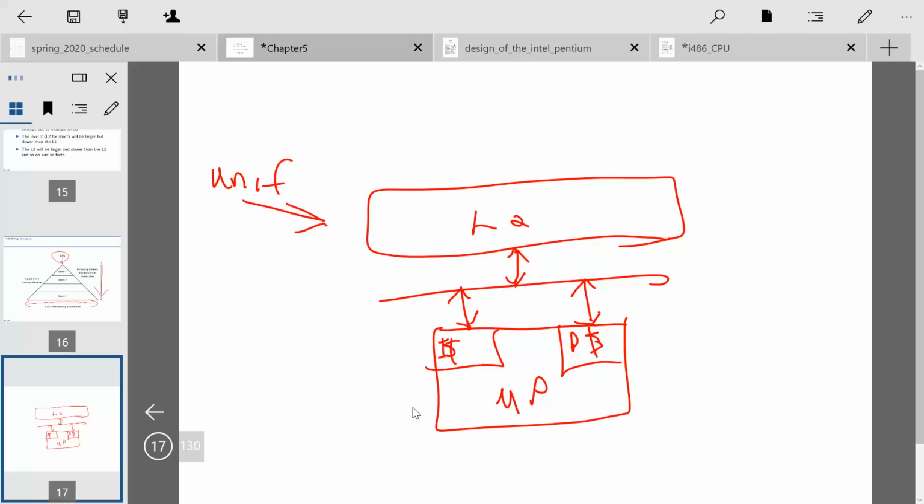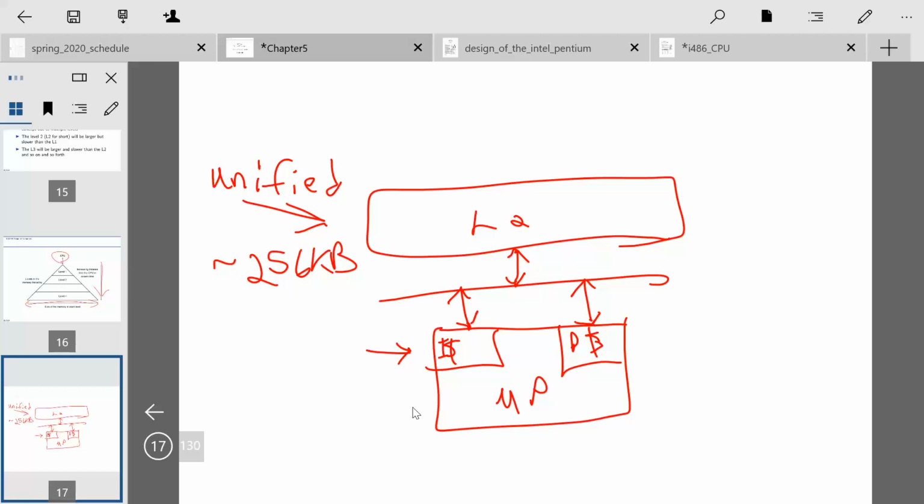I have not really seen a split level 2. It just doesn't make any sense. The level 2, remember, is on the order of 256 kilobytes on a high performance or even a lower performance application architecture. And I always talk about application processors, like the ARM A series of processor, A being for application. They're very general purpose, and so they have what's considered a very typical memory hierarchy, like we saw in that diagram.